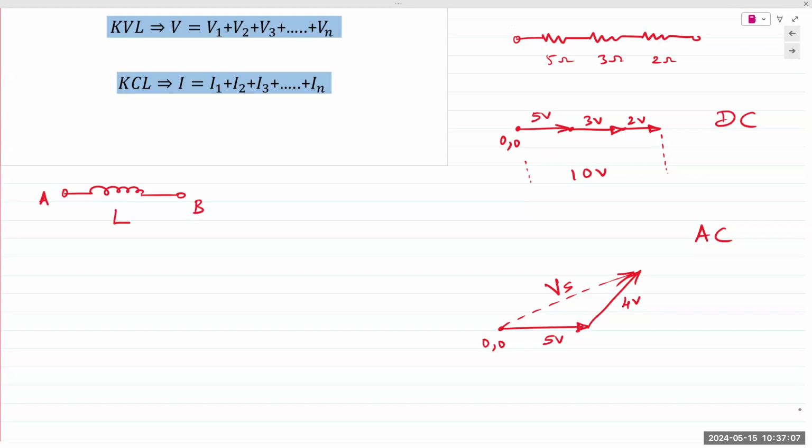Inductor resistance is 0 for ideal inductors, RL is 0. However, real-life inductors have resistance. They are made out of a conducting coil of wire. Any current-carrying conductor inherently has resistance, inductance, and capacitance. The values of these R, L, and C phenomena do not usually rise to the level of interference. However, when it's an inductor made out of a coil of wire, that coil of wire has resistance.